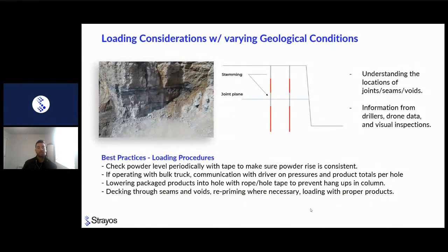If you're putting excessive packaged products within your hole, if it's a wet hole, you might want to reprime, choosing the proper priming products for the products that you're using. These are all good practices when you run into issues subsurface within the geology.